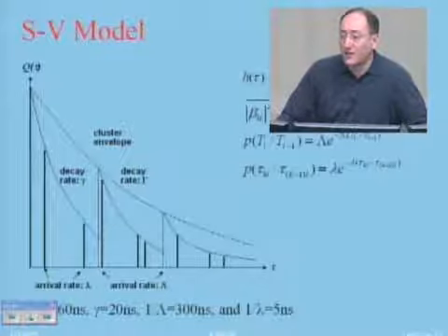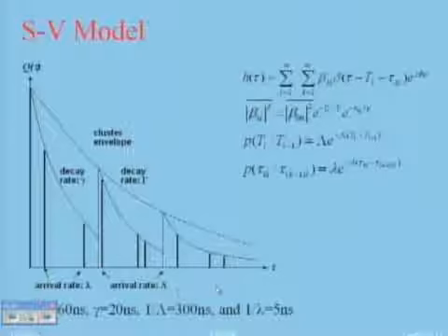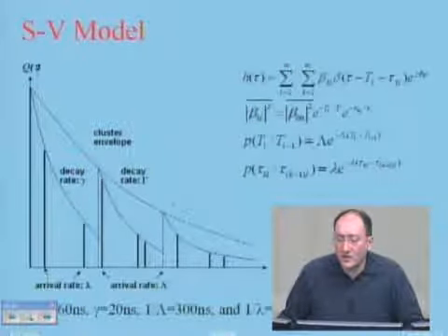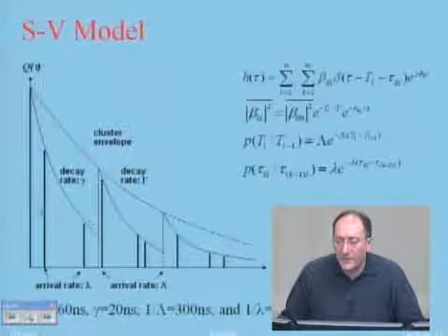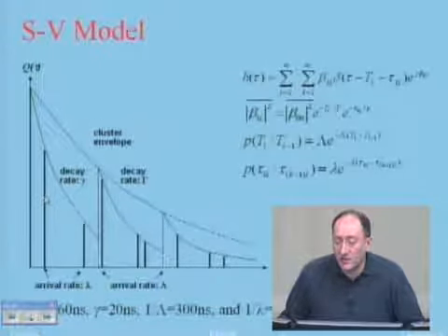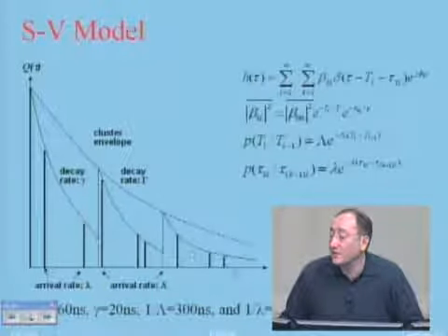Okay. Now, these are equations which relate the path strengths to the distance and to the decay rate. These two. Now, if I want to look at that intuitively, I have 3 clusters in here and path rays within each cluster. The statistics of each of these paths in the Saleh-Valenzuela model is Rayleigh. They assume all of these paths are Rayleigh fading.